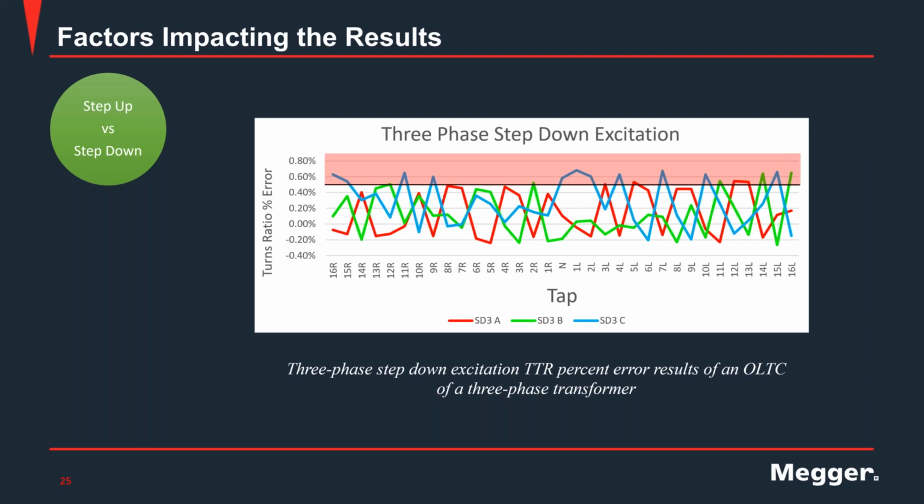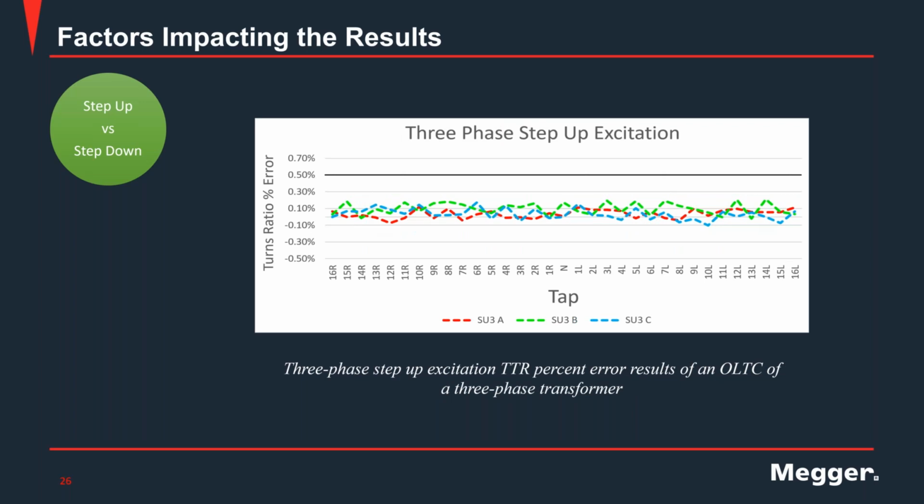Let's look at the same test using step up excitation, energizing the low voltage side of the transformer. We see the error is very small compared to the previous result.